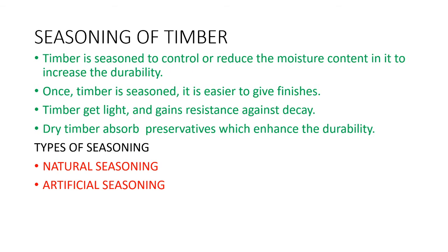Before using the timber in our industry or in our household, it should be properly seasoned. Okay, so what is seasoning? Seasoning is actually to control or reduce the moisture content in it so that the durability can be increased. Once the seasoning is done, it is easier to give finishes to the timber. Timber gets light and gains resistance against decay. Dry timbers absorb preservatives, which enhance the durability.